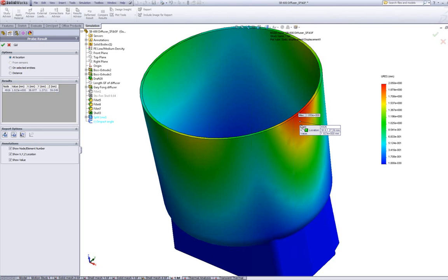So it goes in and samples, and wherever I click, it'll select the closest node possible that's in one of my tetrahedrons. So in this case, you see where my mouse is located. At the very point, there happens to be no node, so simulation chose the node that's right above that, that's closest to my area of selection. In this case, it's going to be that particular node, 4,926. I have my magnitude there, my displacement.